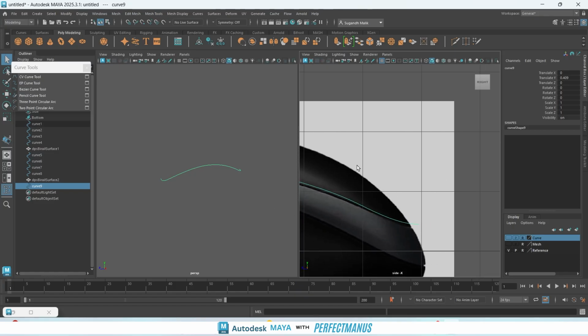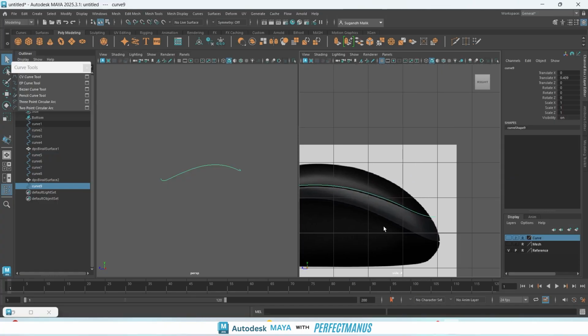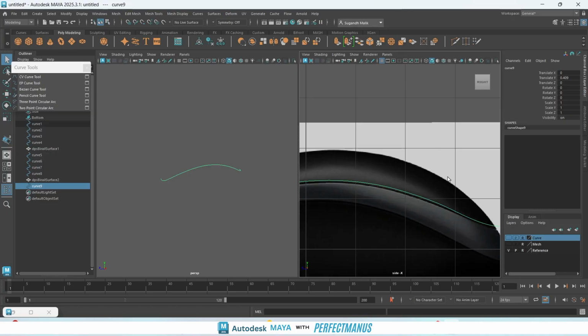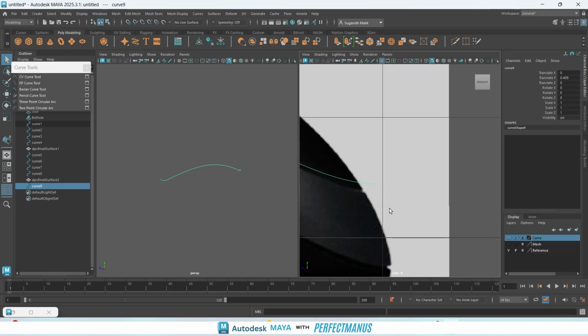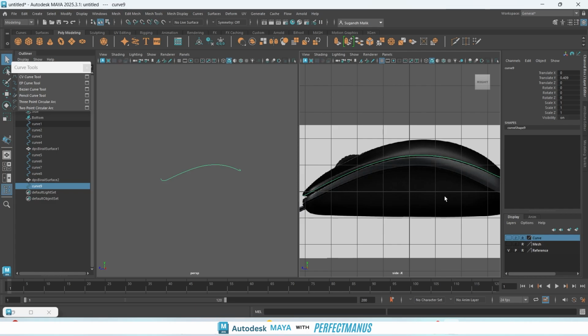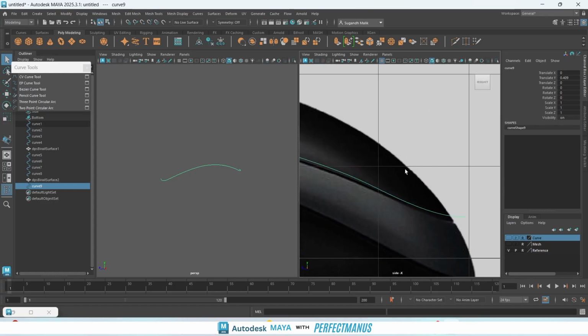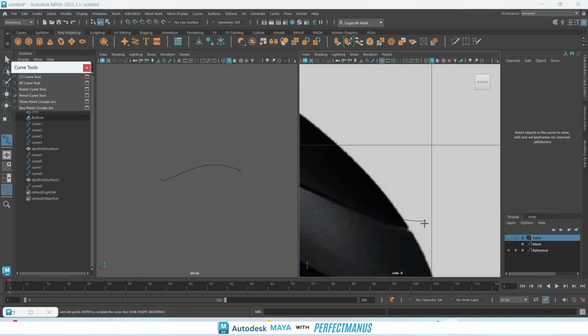This is the one we'll be working with and the top one. So to create this, let's work with back because back is much more curved. We don't need to work a lot here, but we need to guess the shape a little bit because in the end you can see that it's a lot in the back. It's not ended here because we are creating this based on considering that it's in your perspective, or is created or clicked with some focal length of your camera. So here you have to take a guess again. Okay, and just keep checking your basic shape. Even if you change it, until you delete the histories, your curves can control those meshes. Okay, so from here we'll be creating that EP curve.